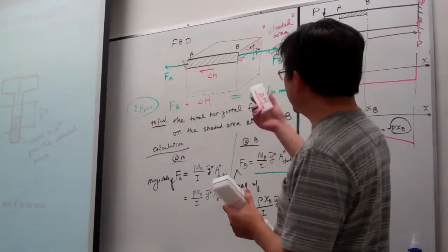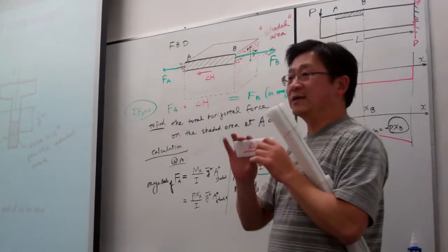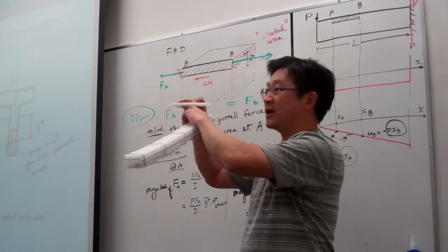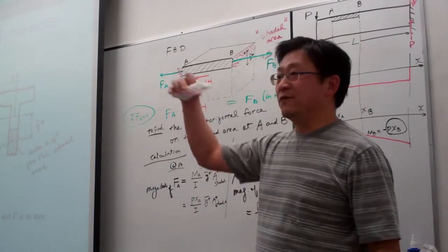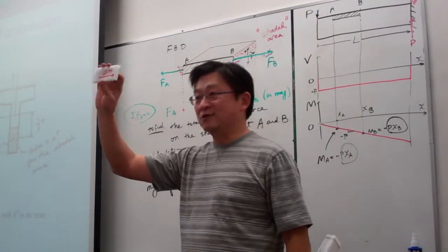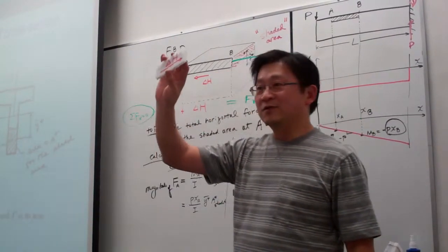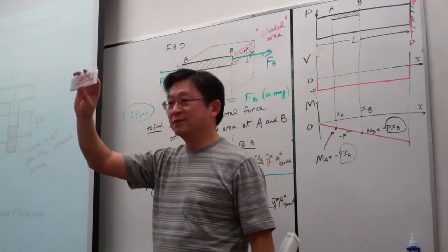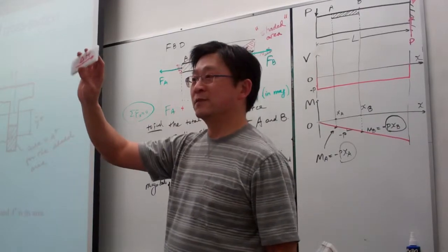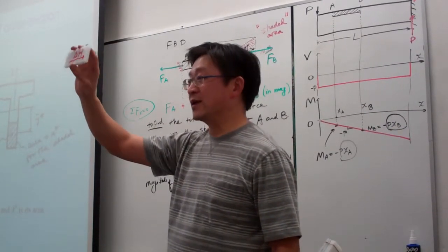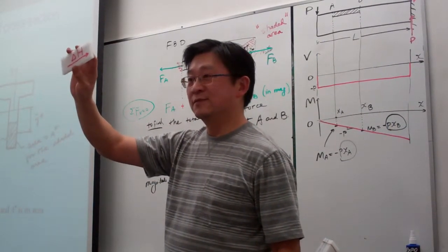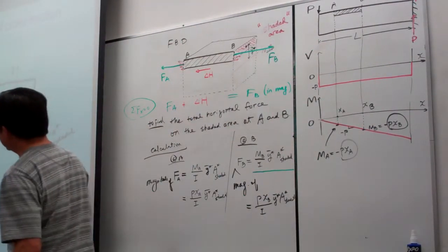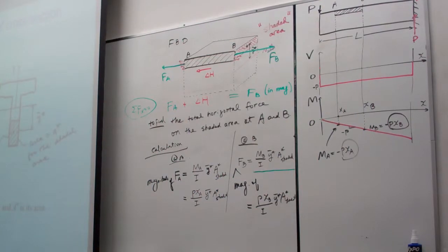So right now that's the delta H, and you realize that delta H is a reaction that exists underneath. So that is a force parallel to this cross section, right? So are we able to calculate the average shear stress over this cross section? How much? Delta H divided by the area of this one, and then we can do the calculations. So let me turn this off.